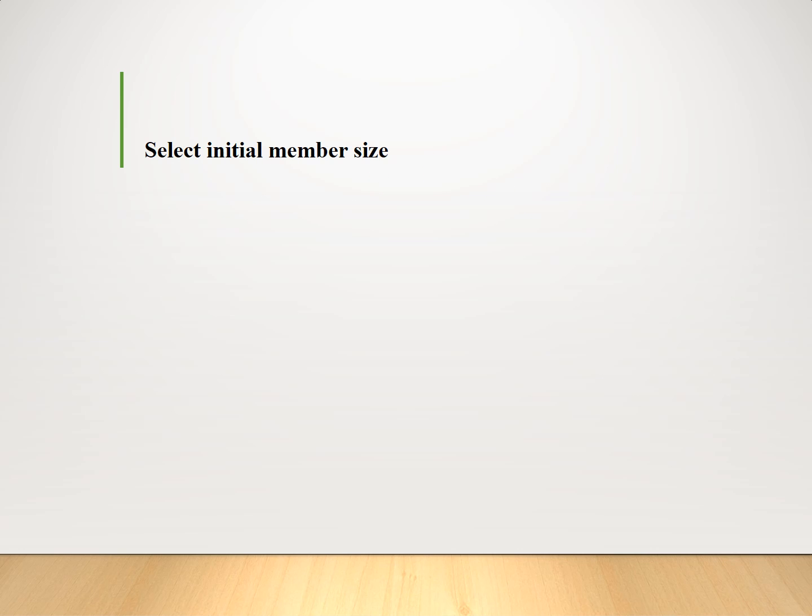First, we have to pick an initial member. Okay, we have resistant moment. Our resistant moment of the member should be bigger or equal to 233 kilonewton times meter, and our unbraced length is equal to 7.3 meters. So we will try W section 310 by 74.